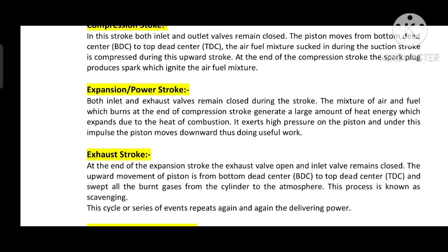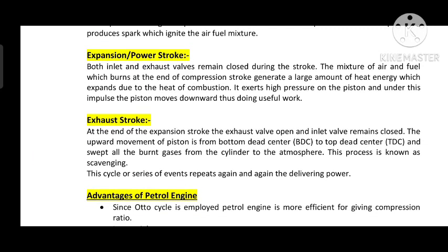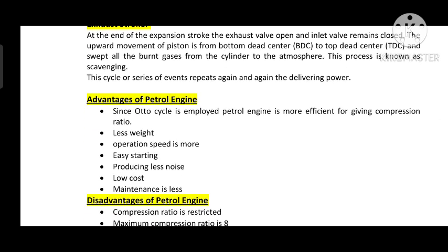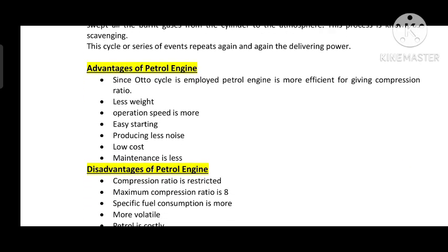Next is your expansion stroke. This stroke is also known as power stroke. In this stroke, both the valves remain closed. The mixture of air and fuel which burns at the end of the compression stroke generates a large amount of heat energy, which expands due to the heat of combustion. It exerts high pressure on the piston.